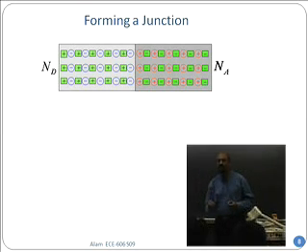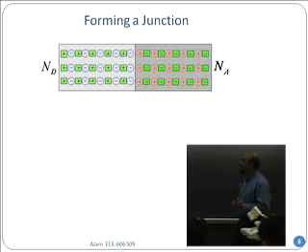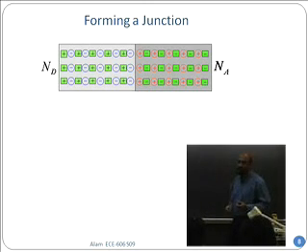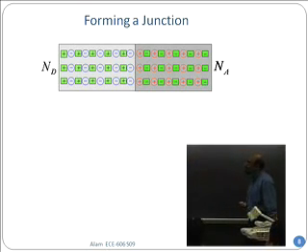And therefore, it has left behind one hole in the valence band, and those holes are with a plus sign in a red circle. Now, the circles can move around. The electrons and holes can move around, but the green things cannot. Those are atoms. Those will be called space charge because they are fixed in space, and therefore will not be able to move around.